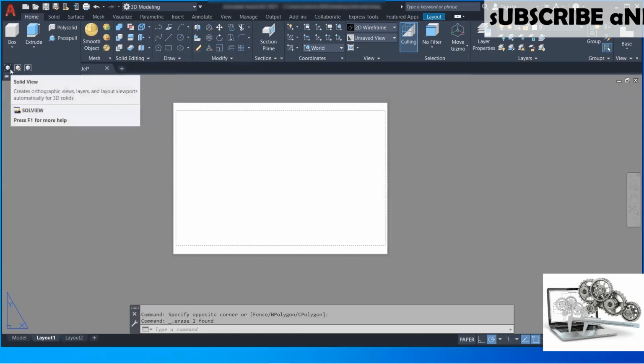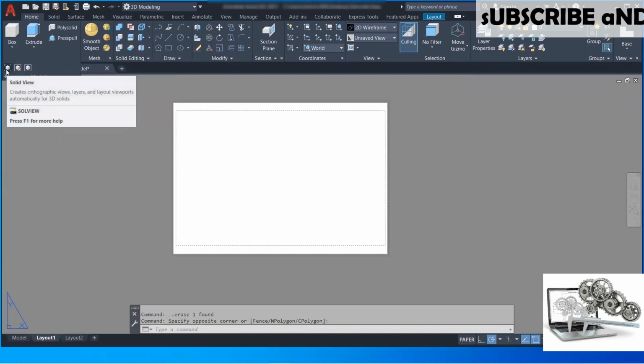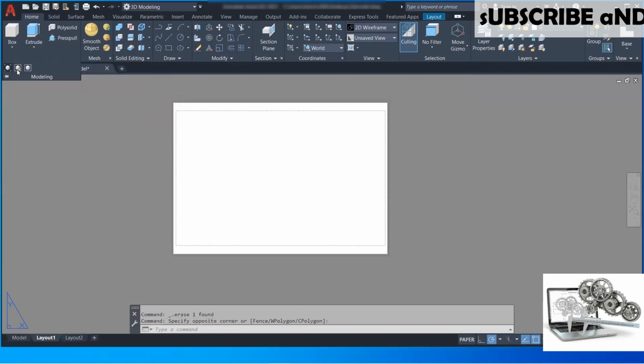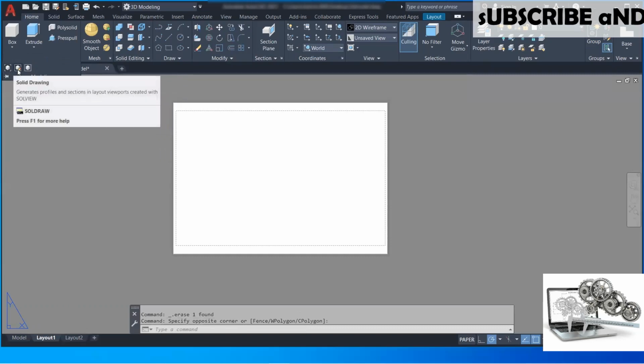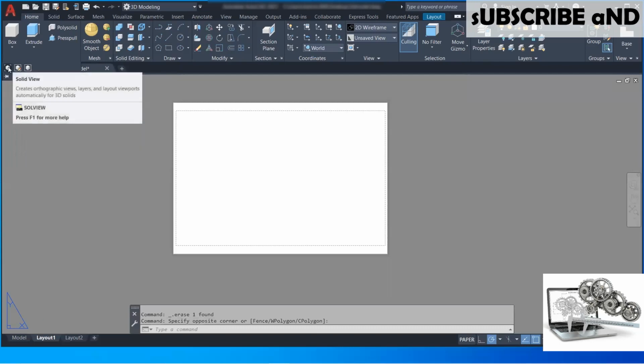We have to create viewports by using the solid view command. So we have to delete this first viewport which is coming by default. Now start the solid view command, and then you can create different types of viewports. This is the solid draw command which is used to draw a viewport. This is the solid profile command which is used to create layers.